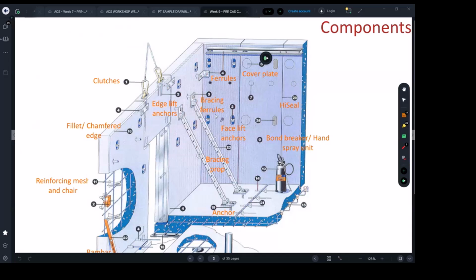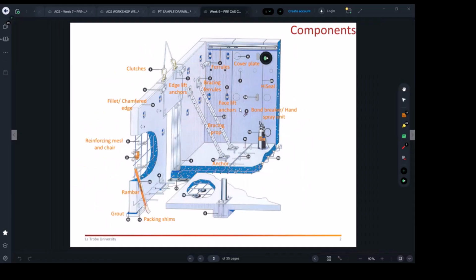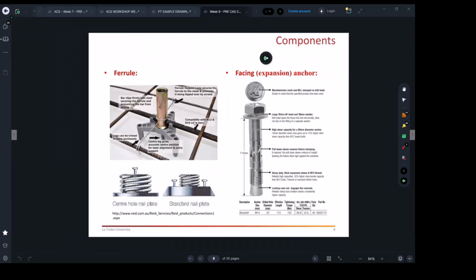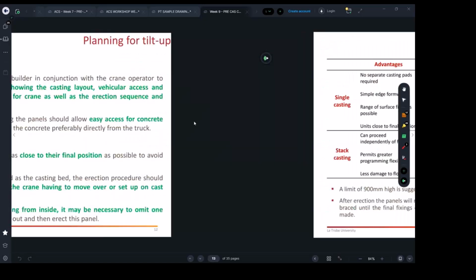So in terms of naming this system, it can be called precast panels. Panels comes from having panel units forming the full wall. Sometimes we call them tilt-up panels. Tilt-ups coming from the concept of having these panels built next to its final position, not exactly on its final position. For example, we will talk about this part here. There is an image coming.